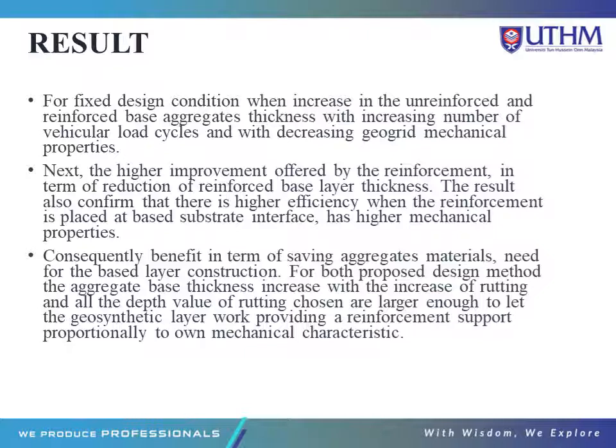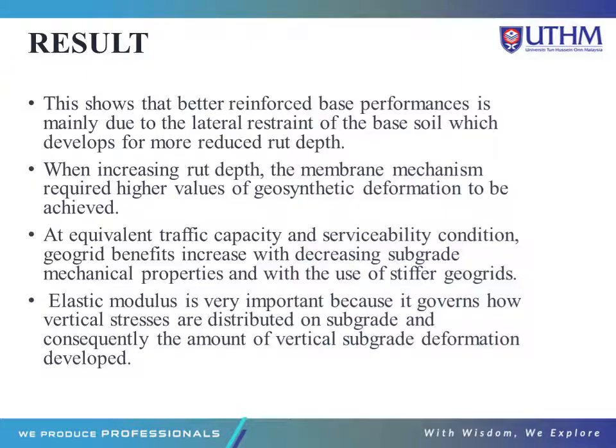For both proposed design methods, the aggregate base thickness increases with the increase of rutting, and all the depth values of rutting chosen are large enough to let the geosynthetic layer work, providing a reinforcement support proportional to its own mechanical characteristics. So this shows that better reinforced base performance is mainly due to the lateral restraint of the base soil, which develops for more reduced rut depth.